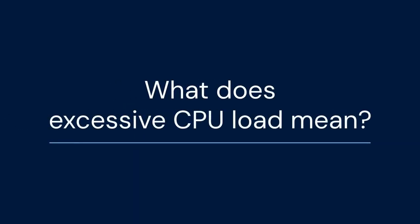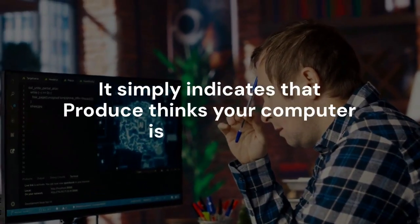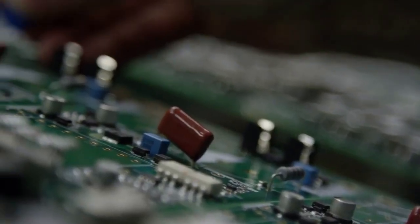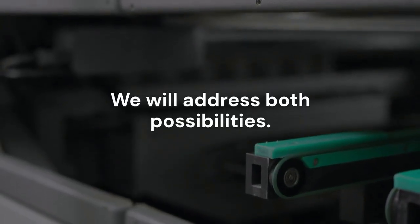First, let's understand what excessive CPU load means. It simply indicates that Proteus thinks your computer is struggling. It believes it is using too much processing power. This can happen due to very complex circuits or specific software settings. We will address both possibilities.